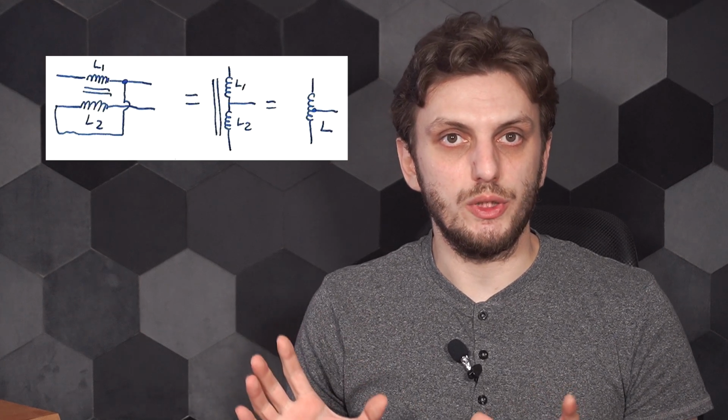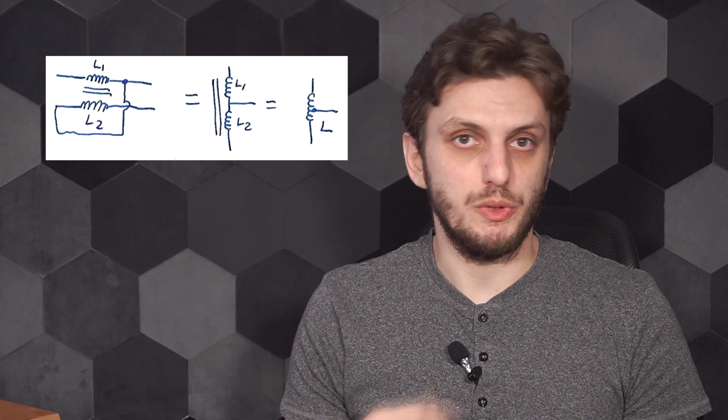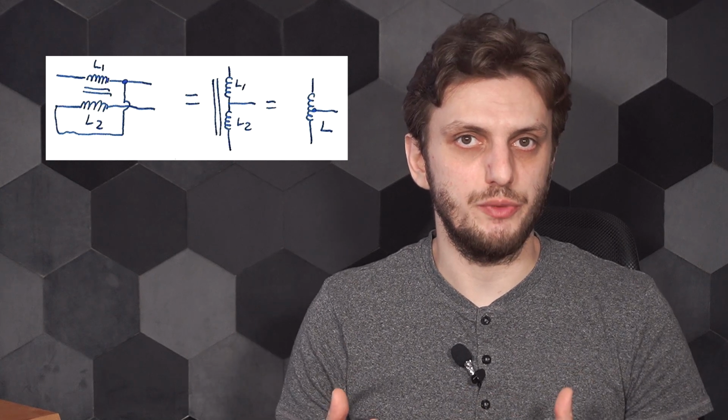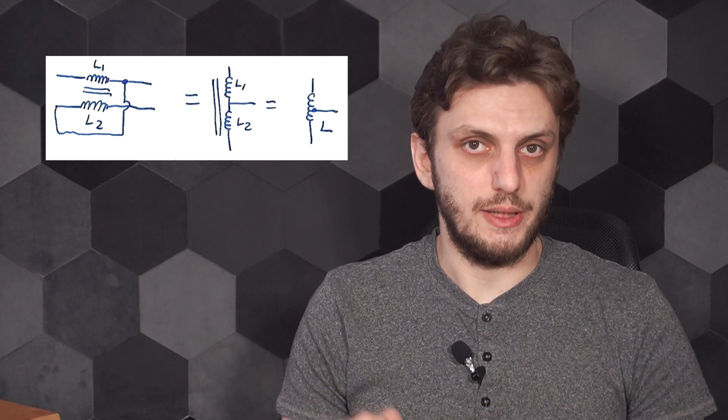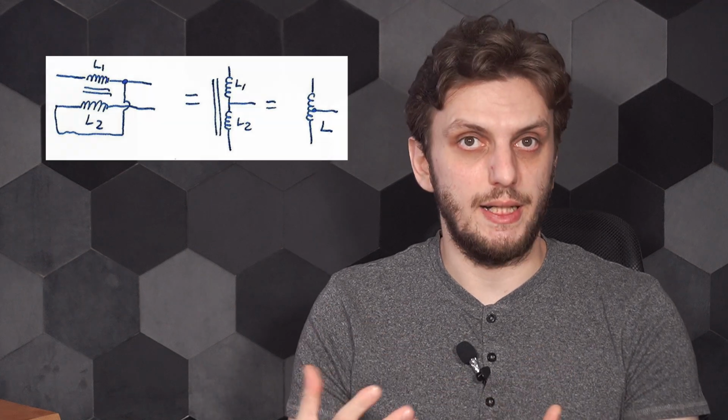Now, since coupling factor is so important, one interesting constructive method is to wind multiple coils at the same time, so to have the turns from the inductors interlaced. So I looked at this a while ago. This coiling technique ensures the highest coupling factor in between the inductors, so it's a superior construction technique compared to keeping the coils separate. You will see schematic designs where you have multiple coils on a transformer interconnected, and these basically form an auto transformer with a specific turns ratio. So from a schematic point of view, it's the same thing as drawing a single inductor with a tap, but this specific drawing method is simply there to highlight the constructive characteristics behind it.